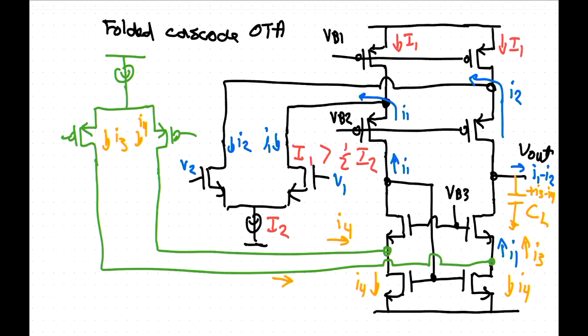Now, the interesting thing is for the PMOS common mode input here, that can go below the negative supply because the voltage around here is going to be about 1 effective voltage across here. So these ones here can easily drop below the negative supply. Now, if you connect the gates up together in such a way that they don't cancel, they will add together, and now we have a rail-to-rail input stage.